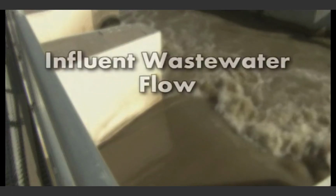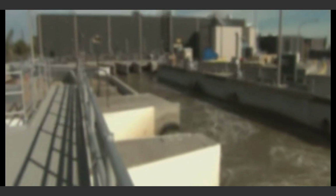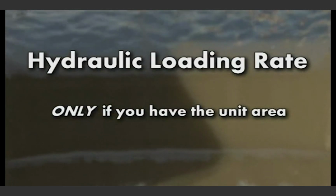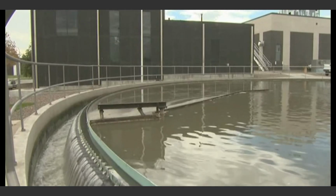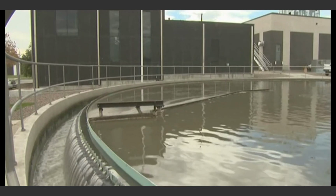The amount of influent wastewater flow is usually measured in million gallons per day, or MGD. It can be called hydraulic loading rate only if you have the unit area, because the unit area is rarely known for a treatment plant. The hydraulic loading rate is typically a process control parameter used for unit processes like sedimentation, flocculation, etc.